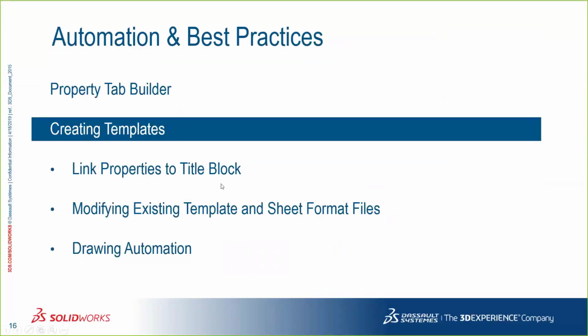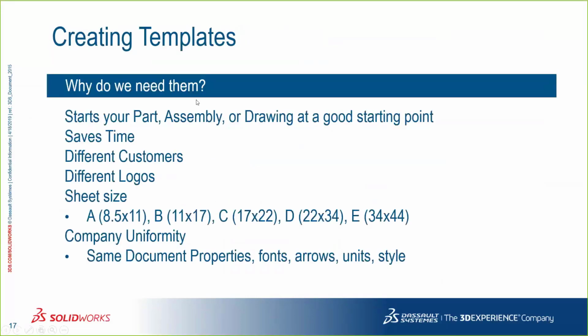So now that we have our property tab builder done, let's check out creating templates. So why do we need templates, right? Again, it's a great place to start your part, assembly, or drawing. A lot of people don't know that you can have planes preset in a part, or your assembly might already have something mated at the very beginning, stuff like that. And it saves you time, right? I don't have to always start from scratch.